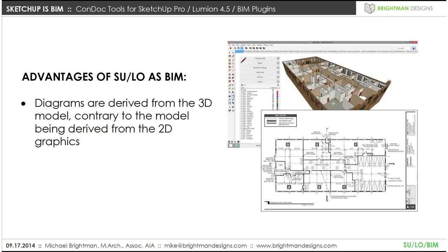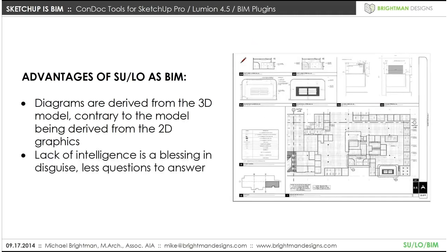Some other advantages are that the diagrams are derived from the 3D. I explained that and demonstrated that pretty clearly, but really where you could compare that is a lot of the other BIM programs, you would essentially be drafting your construction documents, and then your 3D model is a product of that. So I think it's better to think and design in 3D and then have your diagrams as a product of that. So that's the way that SketchUp and layout works, is that you think and design in 3D, and your construction documents or your diagrams are a product of that design model.